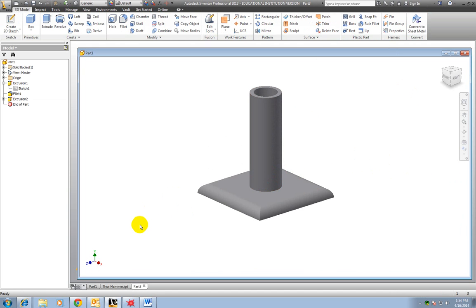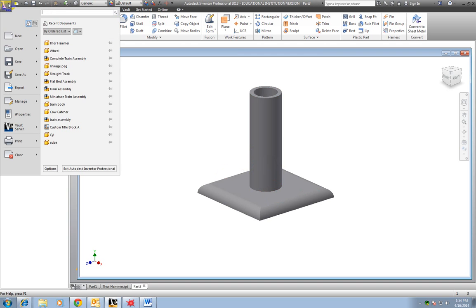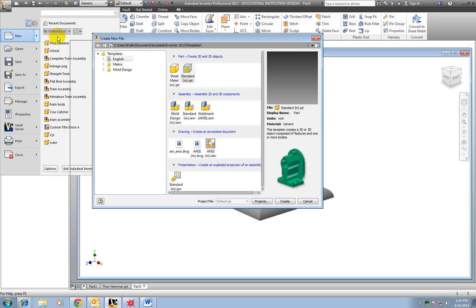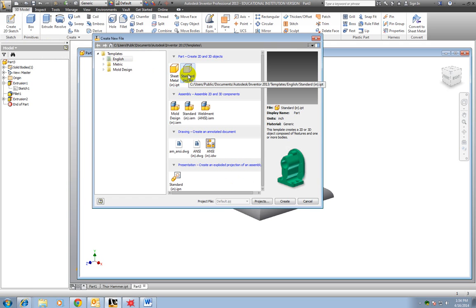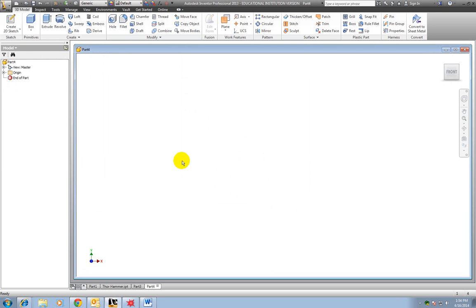Now for the assignment I'm getting ready to give you, I've got a little more to show you, but I want you to use parametric equations to do it. Another way that you can scale the size of a part is this: let me start a new part. Actually, follow along with me. Open up a new part. Then I can go over to where it says Derive.